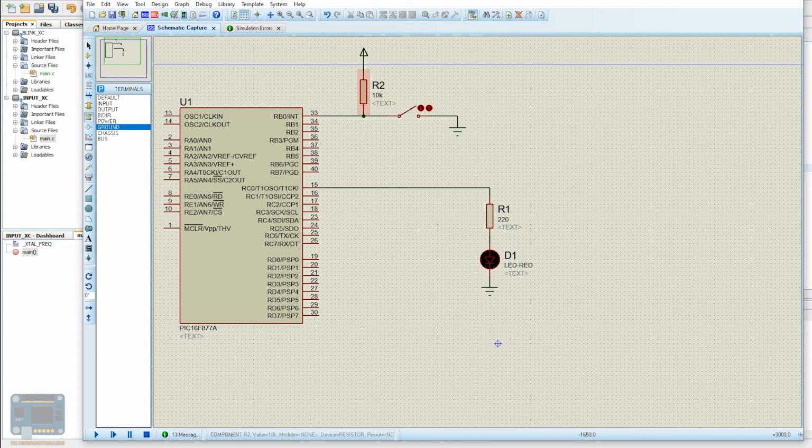So this resistor is actually important, right? We call this a pull-up resistor, and actually the device has internal resistors too, but that's for a later discussion. For now, you should know that when you see a switch or a button, you should use a pull-up resistor like this one. So this is a normally high switch or an active low switch.